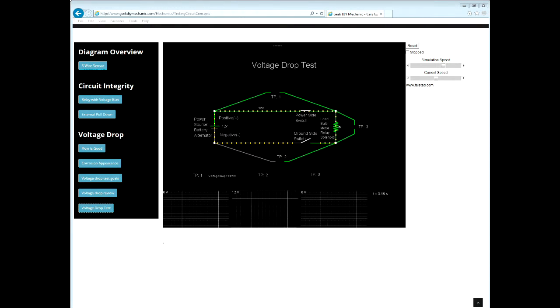Again, for the voltage drop test to produce proper results, the circuit must have current flowing. Sorry for discussing current flow numerous times, but like I said, this is the most common mistake in the voltage drop test, not having current flowing. So let's close all the switches and review what a healthy circuit looks like again.